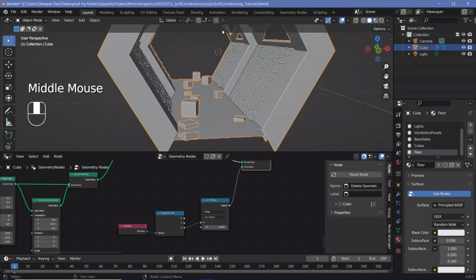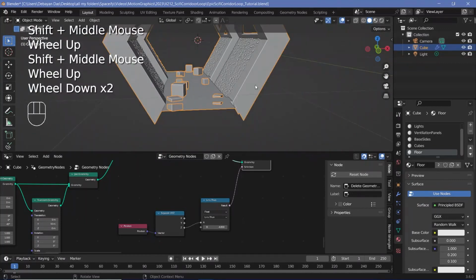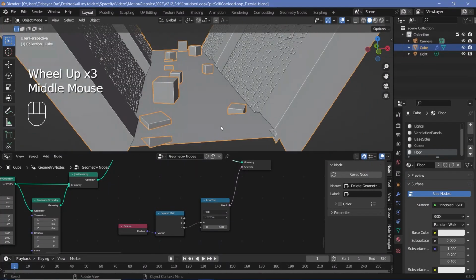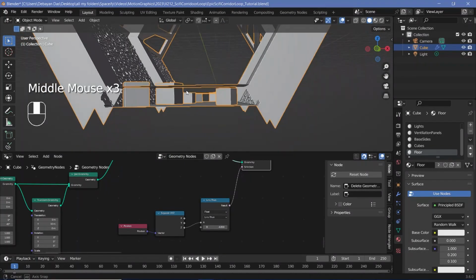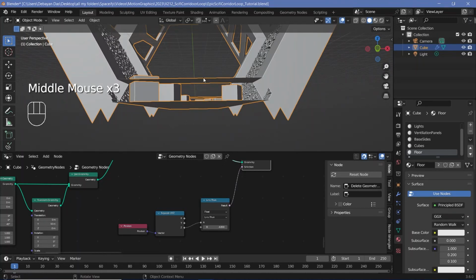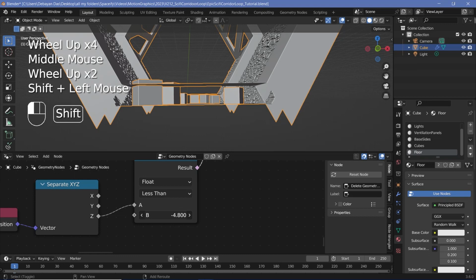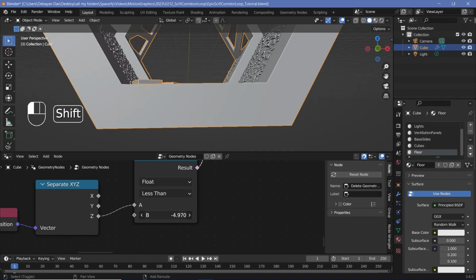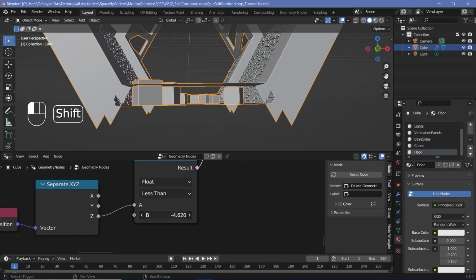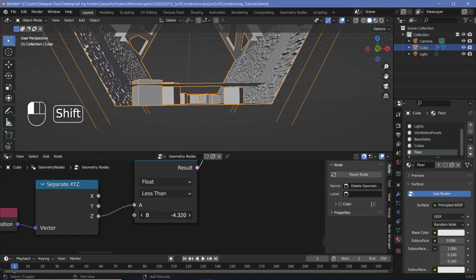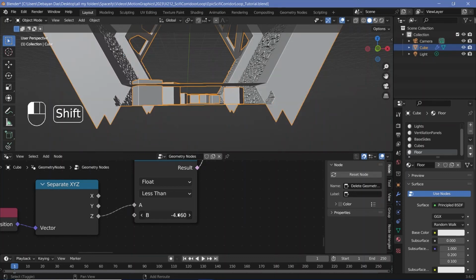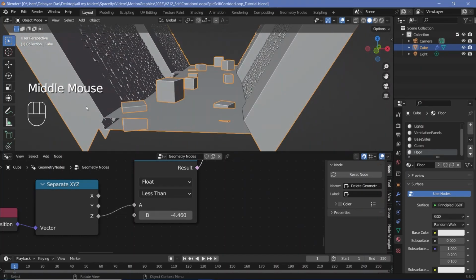And the issue that you'll face is that if these sides are to be present, automatically this top face will still be present. It's really hard to get rid of this particular top face while keeping these side edges. If you actually start reducing this slightly further, everything comes back. So if you start increasing it, as soon as the face is removed, even these sides start getting removed. And in fact, these sides are getting removed before that face gets removed at all. So we have to tell Blender not to delete it if it is a part of these sides.